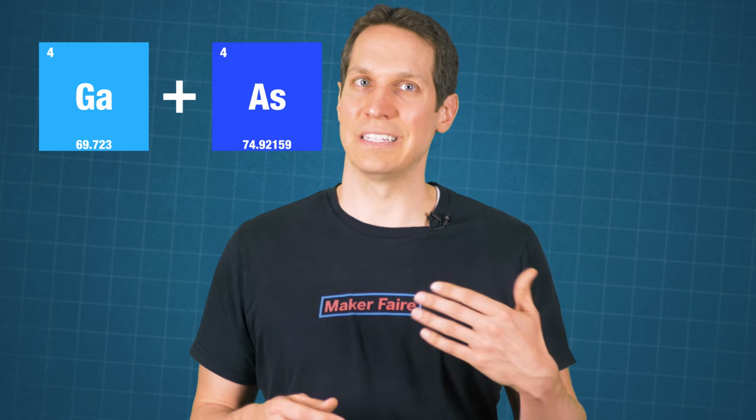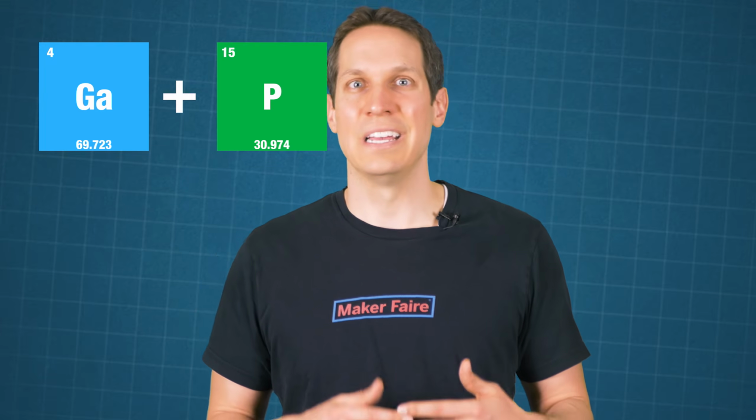It operates the same way a general-purpose or rectifier diode operates, but what makes it emit light is the semiconductor material used in it. The construction of an LED is just the same as a normal PN junction diode. However, instead of silicon or germanium, LEDs are made from compound semiconductor materials like gallium arsenide, gallium phosphide, and other semiconductor materials that emit light. Silicon is most widely used in normal diodes because it is less sensitive to temperature. However, it doesn't release energy in the form of light, but in the form of heat, so it is not used in LEDs.